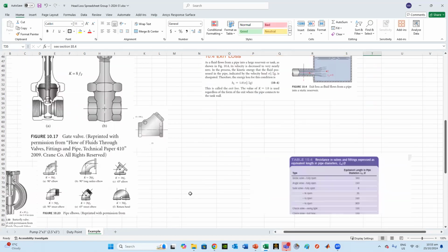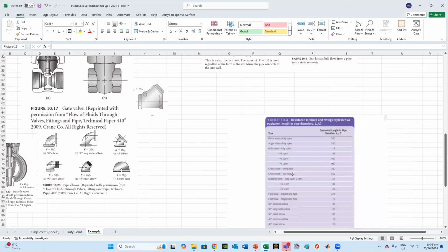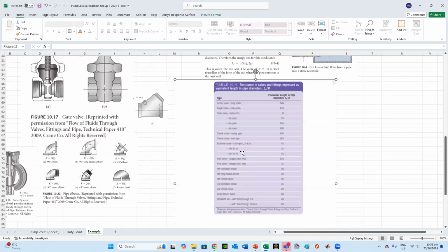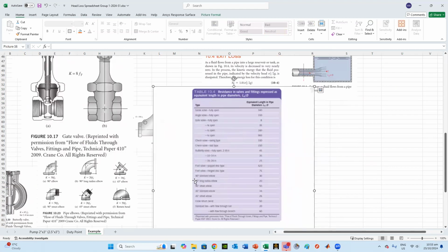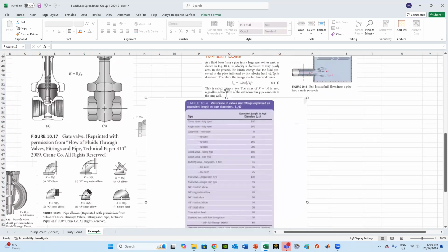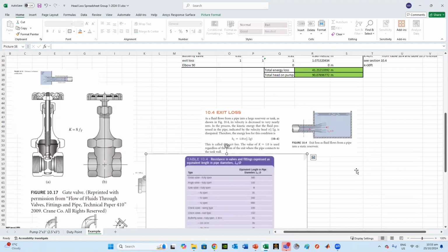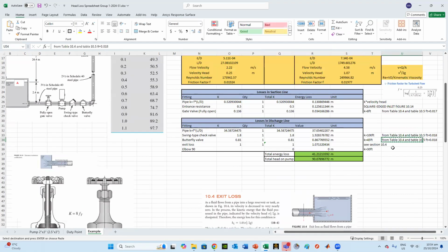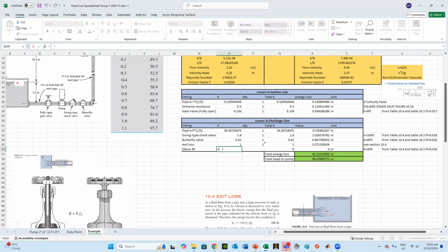The last thing we have from this is elbows. So we come here to this section. Standard elbow 90 degree is saying we choose the value 30 based on this. And so I will copy that line again because that is very important information. So 30 FT. So we come here, we say 30 multiplied by 0.018, and then the quantity is 1.